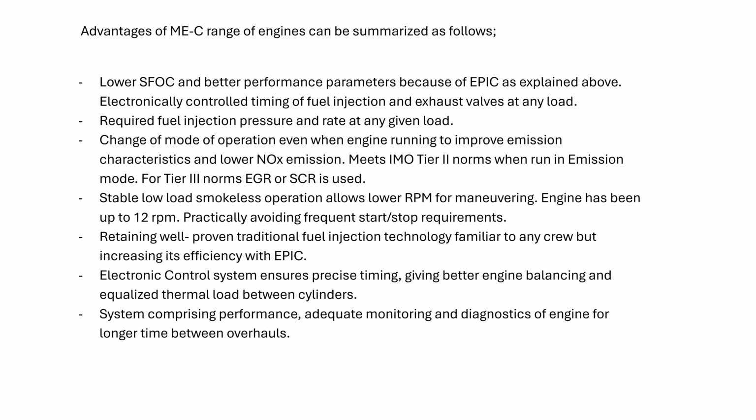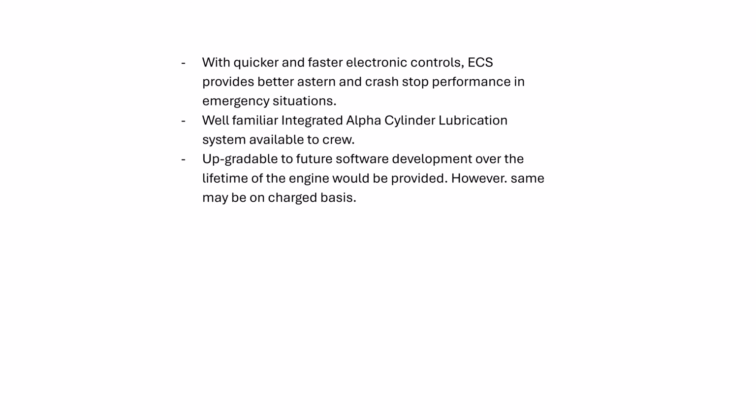Whenever an alarm comes, what is the alarm? What is the purpose of the alarm? How did it come? What needs to be done? What can be done? All is given on the screen. So can the engine be operated by idiots? No, you still need to be a marine engineer. All right. With quicker and faster electronic control, the ECS provides better astern and crash astern performance in emergency situations. Commands are followed quickly. As I said, practically overspeed cannot take place even in rough seas.